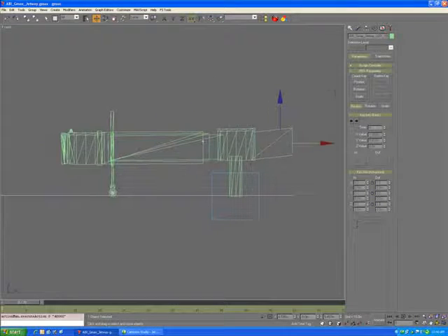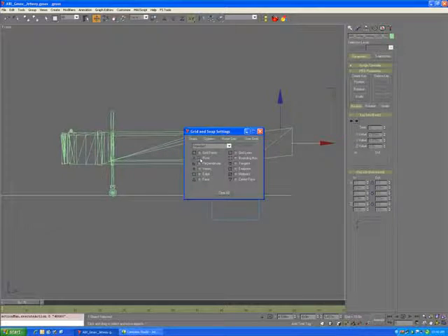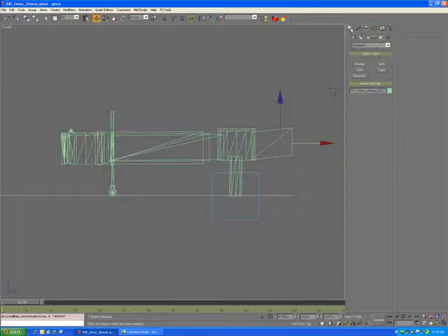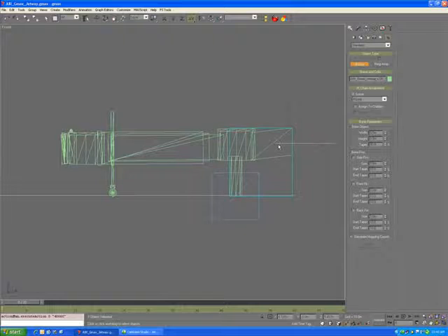So the first thing that needs to happen is you need to create the bone structure for this Jetway. In order to do that, I will turn on the 3D snap toggle down here, and then set the snap toggle to pivot. The reason you do that is so that you can align the bones to the pivots. I've already predefined all of my pivots correctly, so they all pivot appropriately. So when I draw the bones, the bones themselves will align to the pivots. So I'm going to select bones, and I'm going to choose the side view.